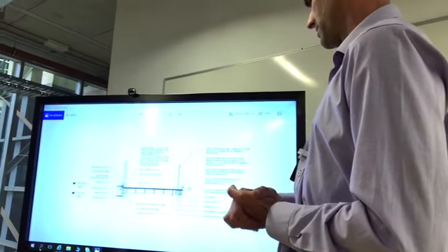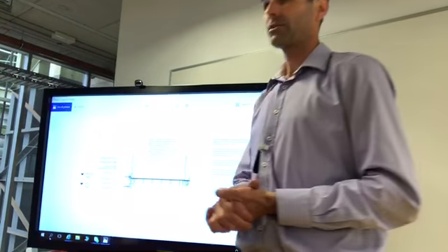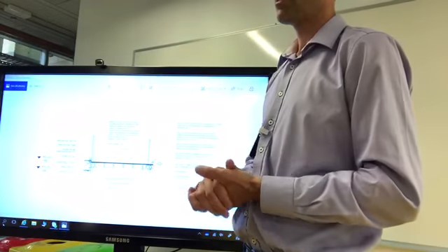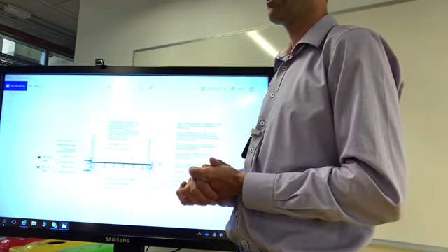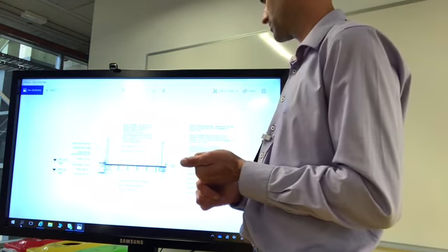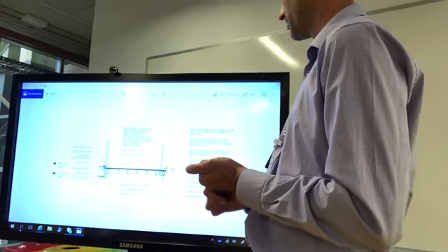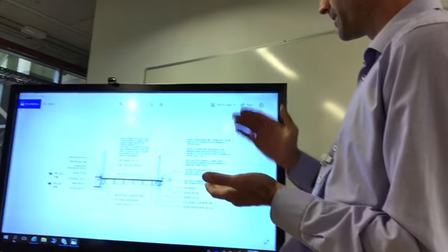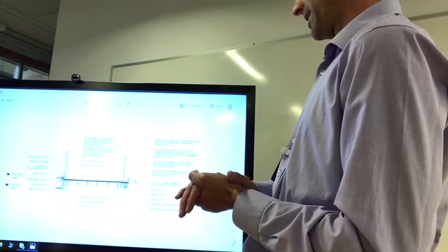Other aspects that are going to be the same: obviously you're going to have a balustrade, minimum 1 metre in height, and your baluster spacing is the same as normal, a 125 millimetre sphere not to pass through.